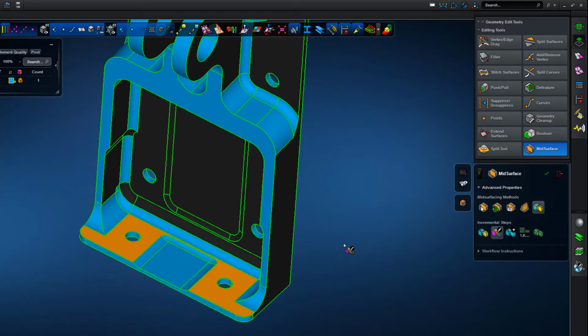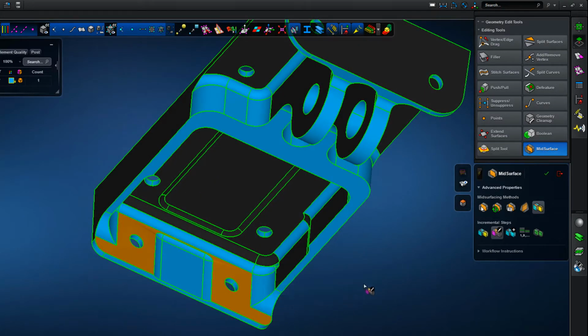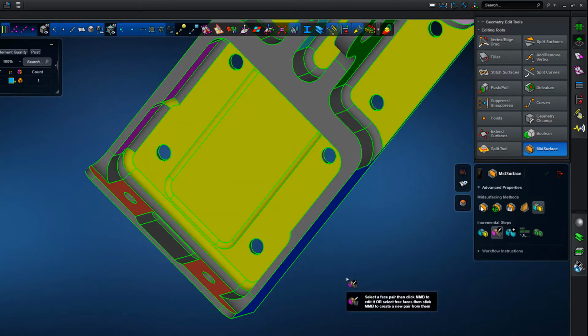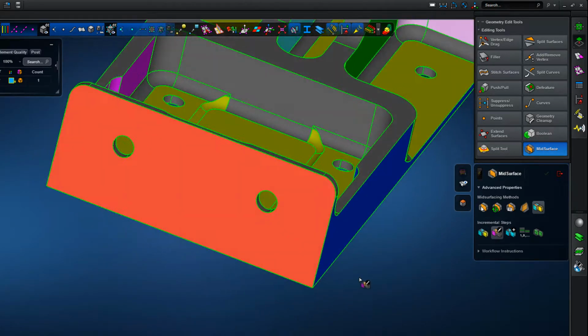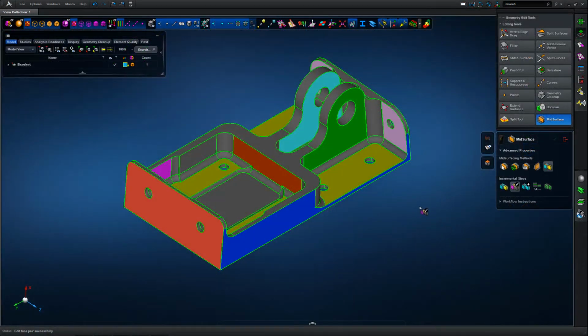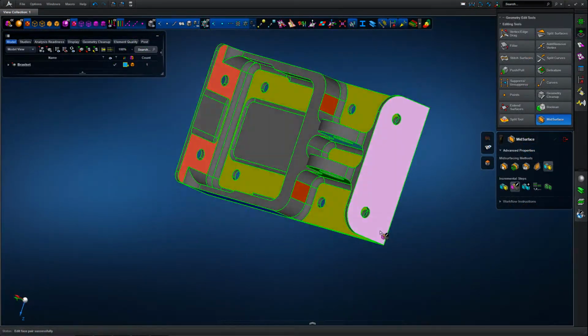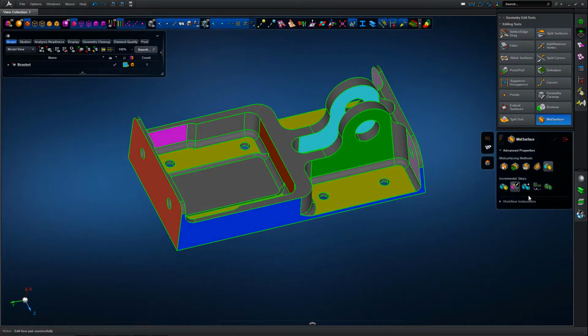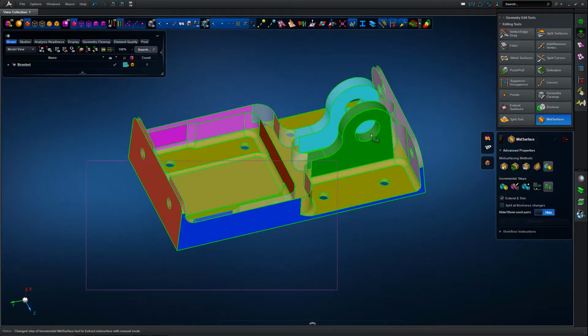We want to take out some local details such as fillets and small surfaces out of the structure, or out of the pair rather, so that the underlying surface is created without any local bumps where the fillets exist. So we work our way around the model with the automatic pair definition, and then some manual edit to those pairs to give us the underlying mid-surfaces that we want.